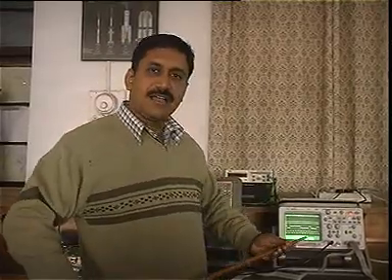So on a given channel, I can either use amplitude shift keying, I could use phase shift keying, I could use frequency shift keying. Out of these three modulation schemes, frequency shift keying is not bandwidth efficient, because for each additional symbol that I am trying to transmit, I need an additional frequency. So in a given channel, I'm going to consume all the possible frequencies. This modulation scheme is not bandwidth efficient. Okay, so this is very important for us to understand.